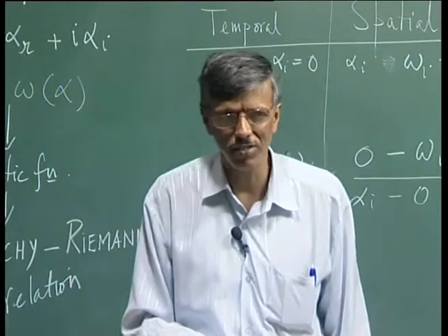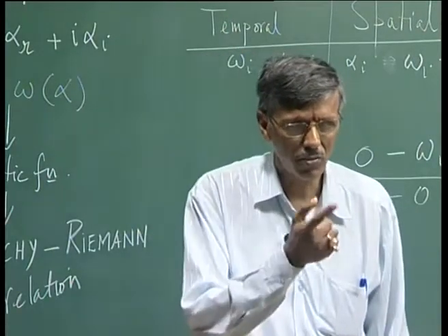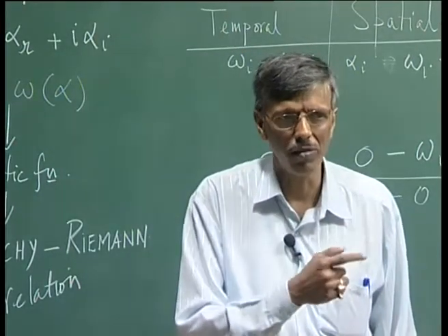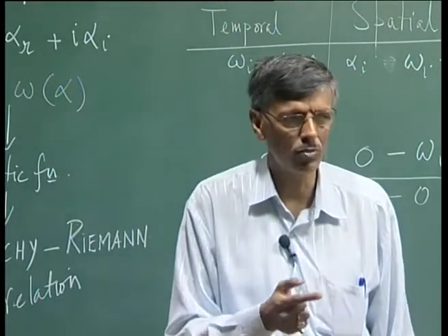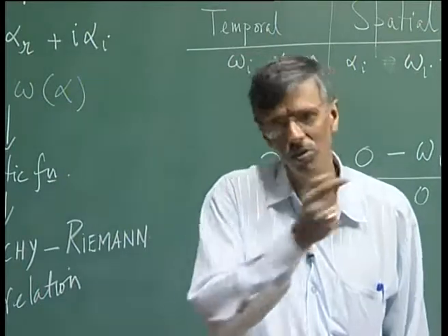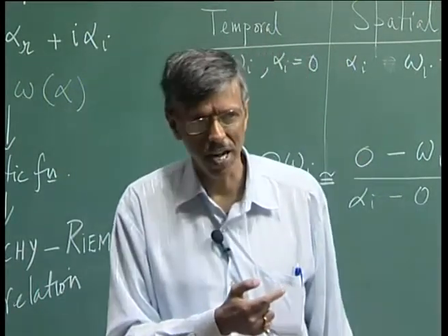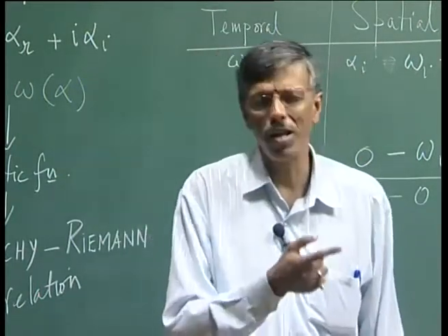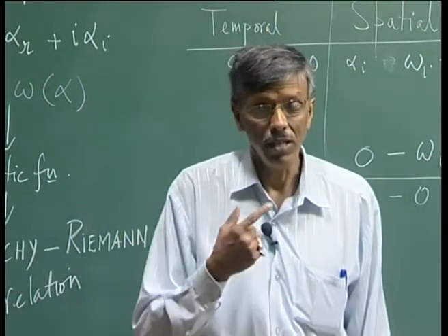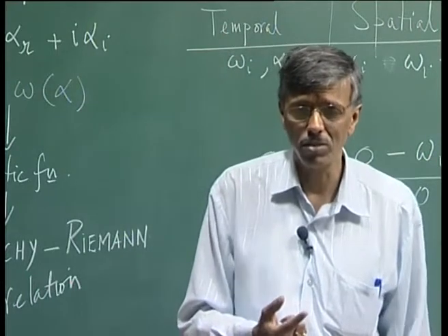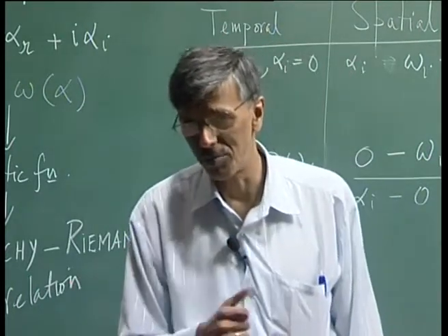Well, you can very clearly see that your phase speed is given by omega by alpha, if you are talking about 2 dimensions. So, if I get that as negative, that means what? The phase will go in the opposite direction. Okay? Well, similarly, one can talk about the group velocity, and one can truly find out if the disturbances are going downstream or upstream, right.